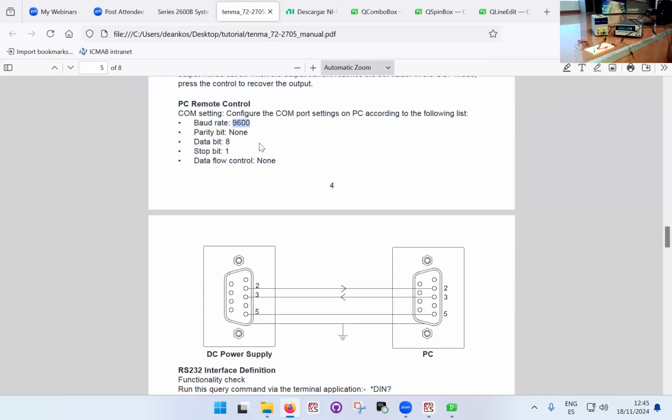This is the frequency, the number of bits per second that you are exchanging with the instrument. So this means that it will be able to send 9,600 bits per second. This is a very standard number for applications where speed doesn't really matter. It can go to very large numbers, around 1 million or so.